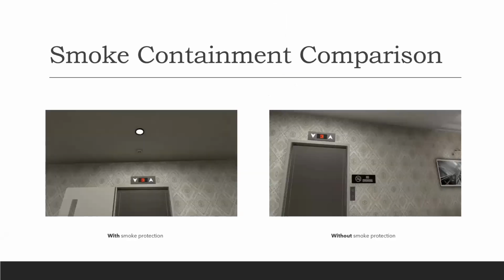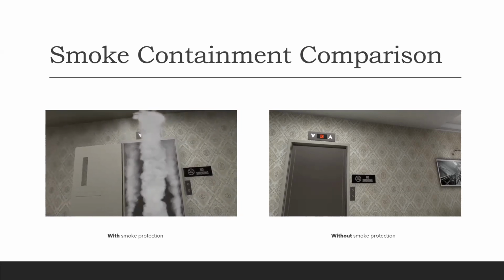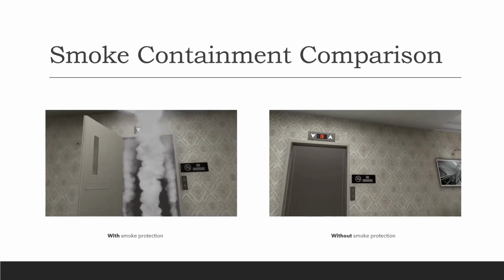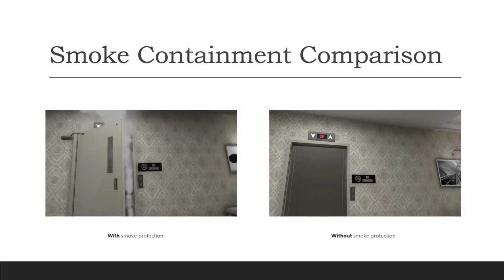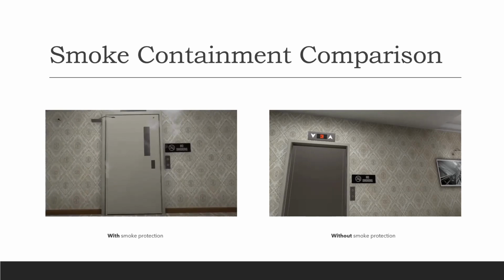So this is actually a video of a virtual reality experience. Hopefully one day we get to cross paths and I have my VR headset with me so you can try this out. But with smoke protection at the elevator shaft, you're going to see that the door system is going to close, containing the smoke inside the elevator shaft. Now the door system is triggered by the smoke alarm and it will close and latch on its own.